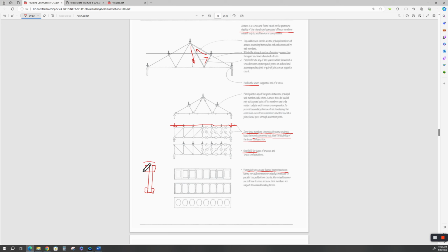So, what would these two 2x4s up here be called? That would be the chord. And that's the bottom chord, right? Okay. And this is the web, all right? Now, before you go drilling and poking holes in here, you got to be careful about stress concentrations.